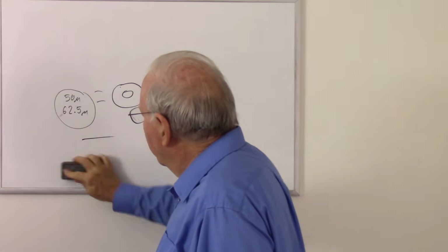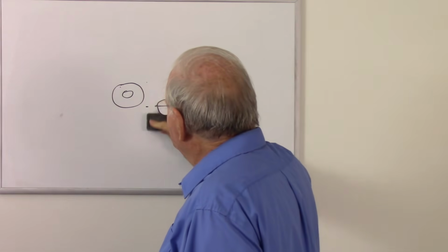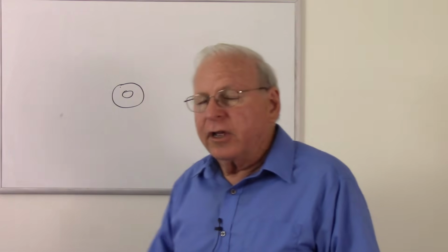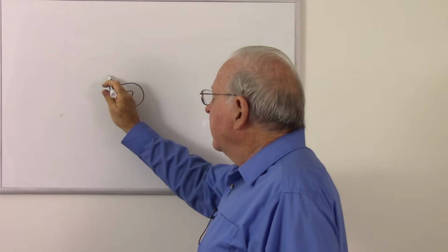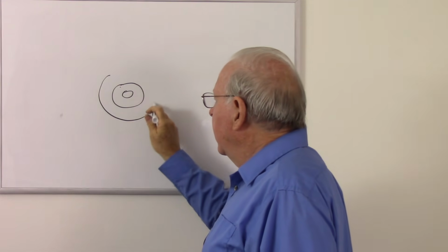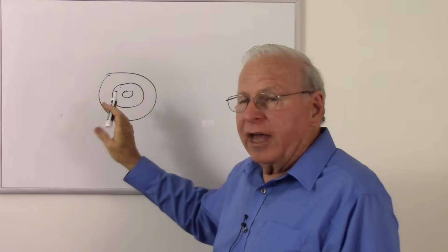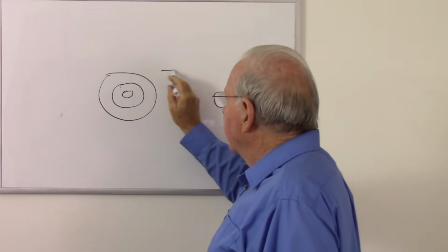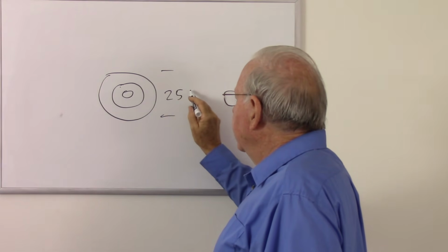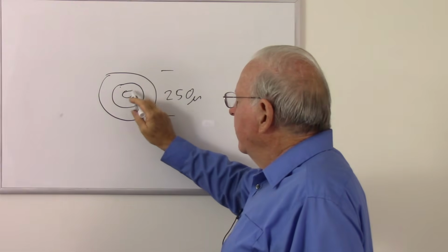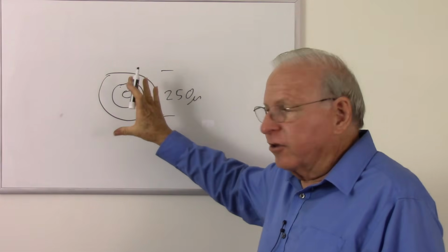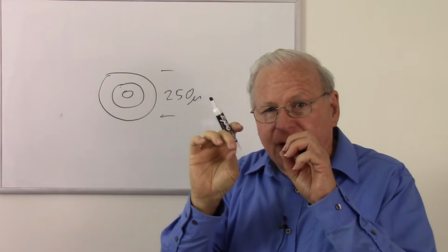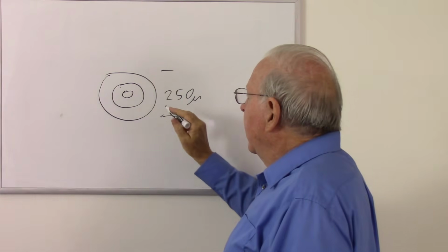Okay, so there's your core and your cladding. And then around that there's going to be what's called the buffer. So there's going to be a primary buffer, which is usually a clear plastic, clear acrylic. And that is usually twice the size of the cladding, so it's going to be 250 microns. So whatever the size the core is, 125 microns for the glass cladding, and remember, they're one piece of glass, so you don't separate them.